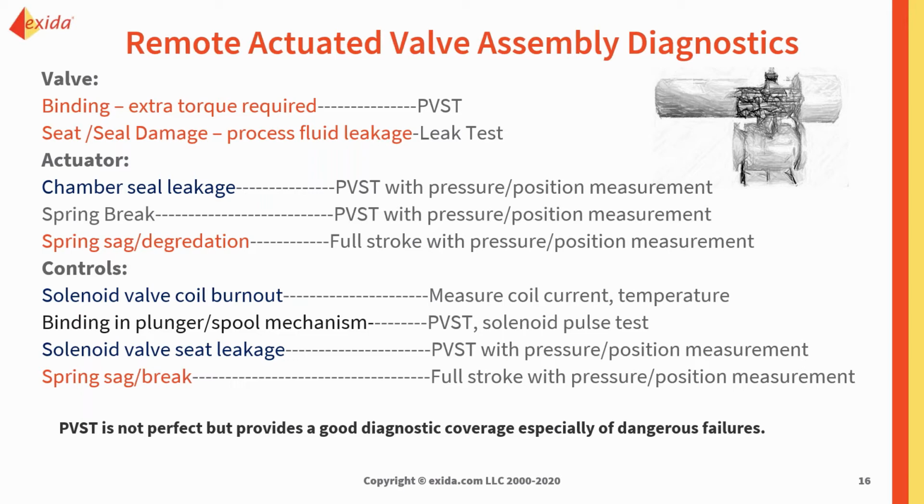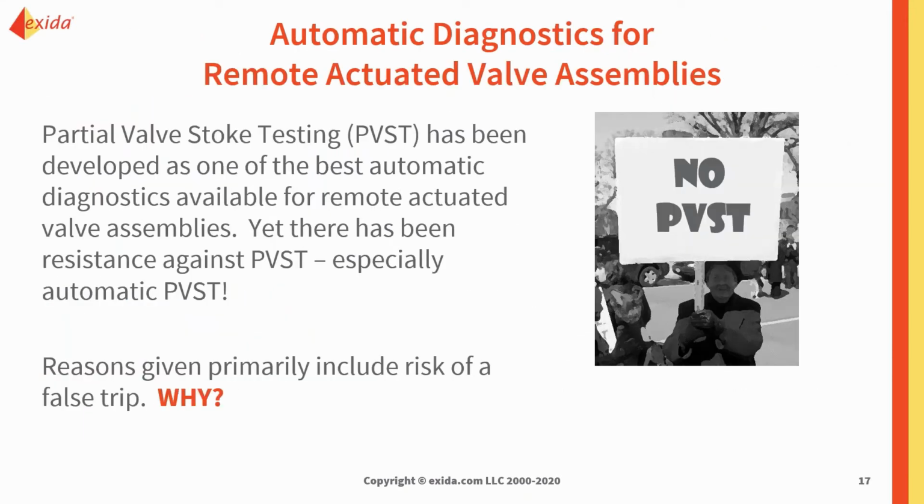Well, let's find out, and let's do some quantitative analysis to determine that. So I think we're finding that PVST looks really good. It's one of the best automatic diagnostics available for remote actuated valve assemblies, and we've definitely seen that PVST detects some of the most dangerous and common failures.